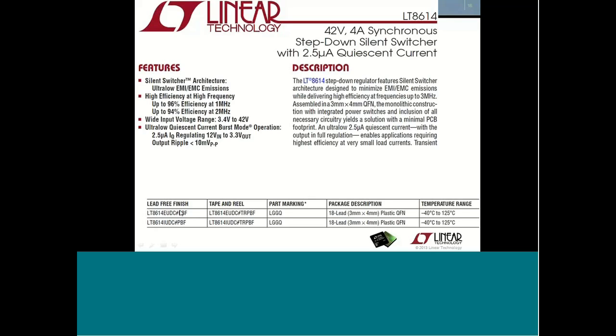The first one, here at the bottom, is described as E, meaning extended temperature range. The second one is rated I, industrial, but you can see on the right-hand side that the temperature range is exactly the same. The difference between E and I comes from testing.